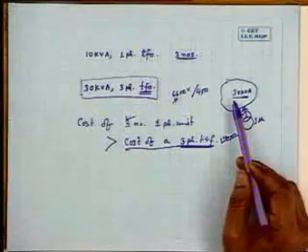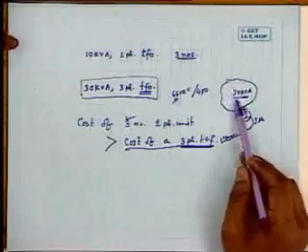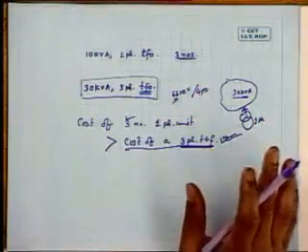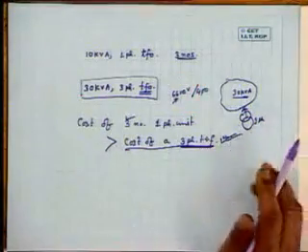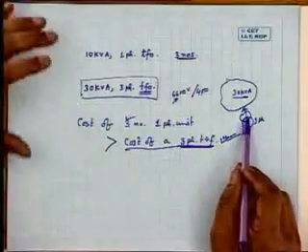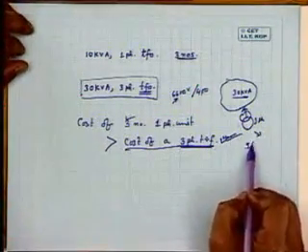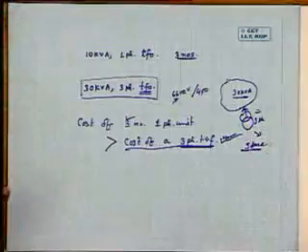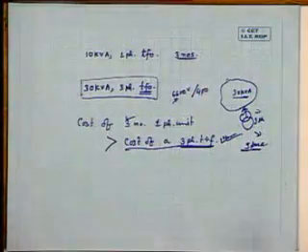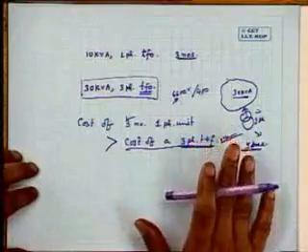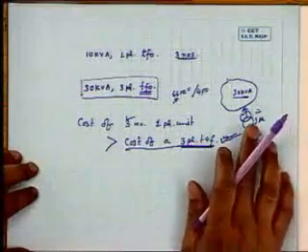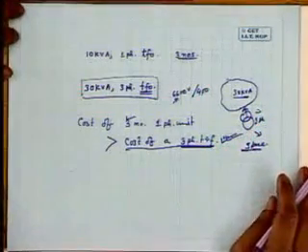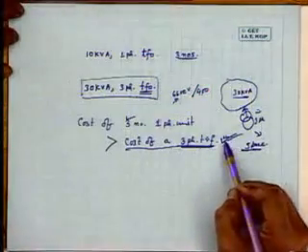Then the total load has to shut off. No power can be given to these consumers now. So what is done generally to maintain a distribution system nicely: whenever a transformer is there, there should be some spare available to you. Suppose this transformer develops a fault, then you must have a spare transformer. At least after 1 hour you can restore the power by disconnecting this faulty transformer and bringing that spare one into service. That is the way it is done in a practical power system.